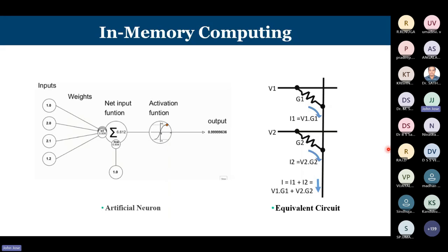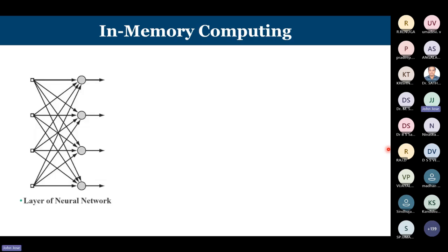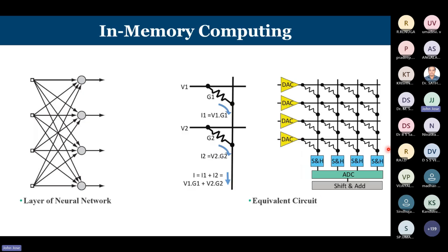What I'm trying to do is represent the weight matrix as memristor values. These are the different layers of the neural network, and I can represent them like this. You have a DAC, a digital to analog converter, since your input values are digital. The sequence of memristor arrays will equally represent your weight matrix. Input values are converted to analog form, and when this analog signal propagates over the memristor, current is produced, and then ultimately you shift back from analog to digital.